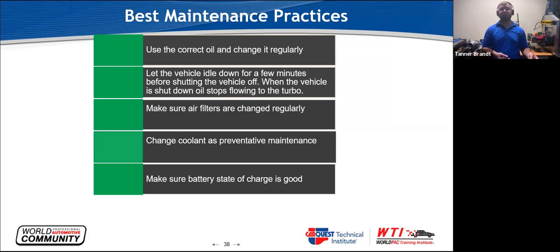On GMs, GM will run the fans after the vehicle is off to try to help cool the turbo. If it feels the battery is too low, it's going to turn those fans off to try to save itself, or maybe it's just going to die. So if the battery is not healthy, there's a chance that you can ruin the turbo, as weird as that is. So that's something to think about.